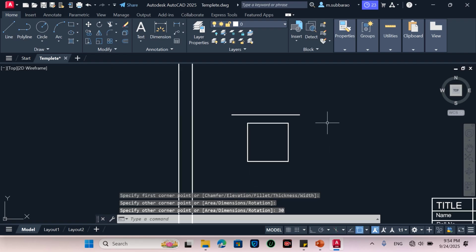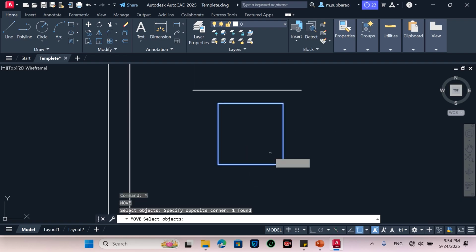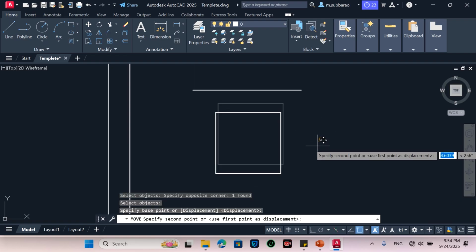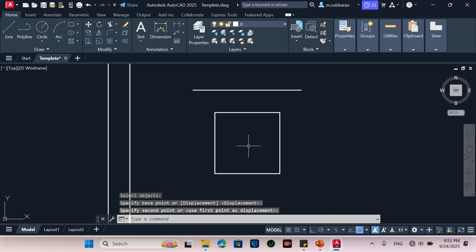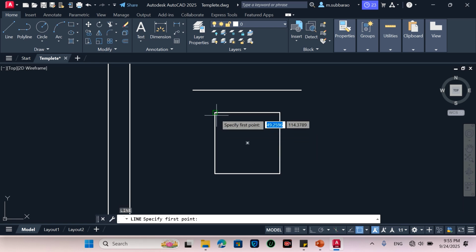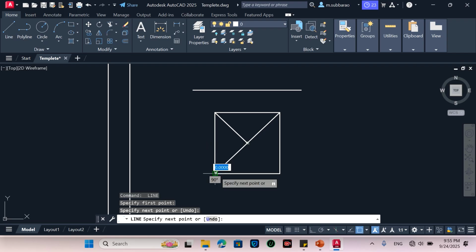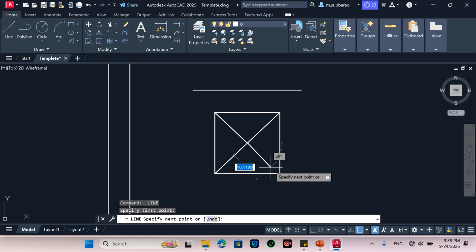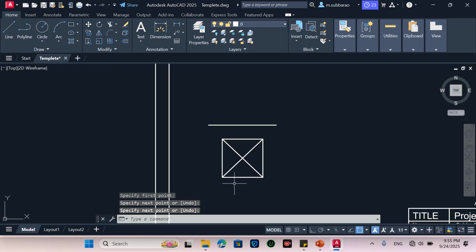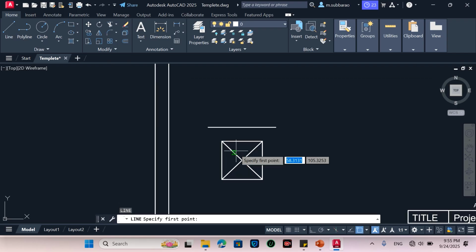So this is the base, and because it is a square pyramid consisting of an apex, the apex will be somewhere at the center. So I need to draw the slant edges from the apex. If I join the slant edges from the apex, it will look like this. So this is the top view, and now I will draw the front view by projecting the lines from the top view.